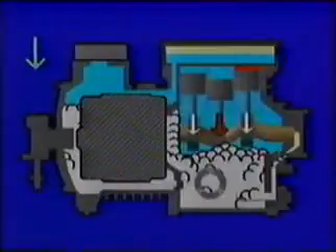The damage shows up as erratic wear or scoring patterns in the lower connecting rod and crankshaft bearing surfaces. This wear opens up the bearing clearances and causes lower net oil pressure over a period of time. With flooded start damage, you frequently find one rod and crankshaft throw scored or seized, with the other bearing surfaces on either side in good condition.